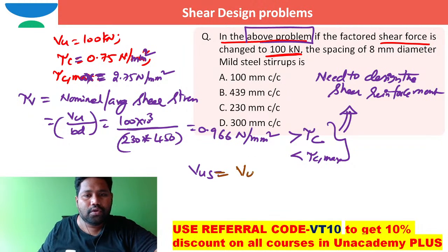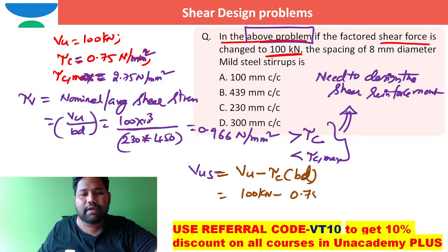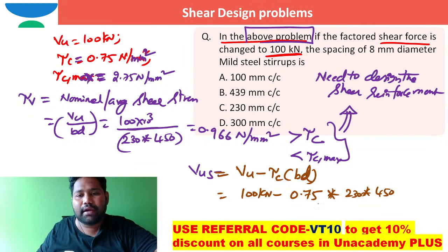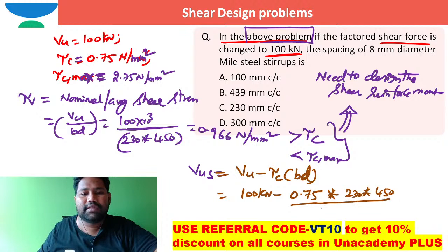Vus is equal to Vu minus tau c times b d, which is Vu is 100 kilonewton minus tau c is 0.75 Newton per millimeter square into b. b is how much, brother? 230 millimeter, d is 450 millimeter, divided by 1000. Then I will get this in kilonewtons.